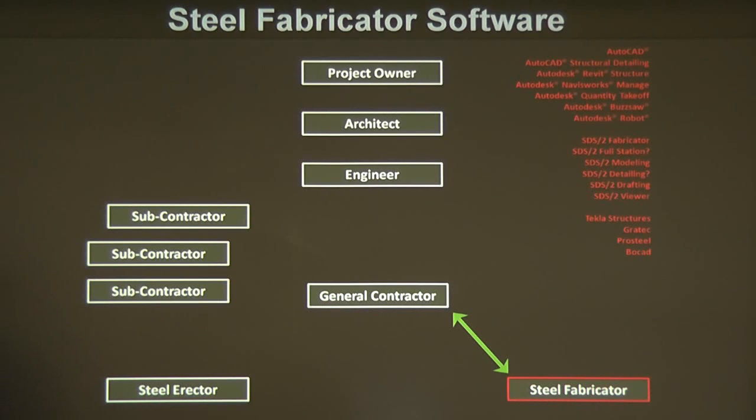The ideal situation is I don't want to get a set of 2D drawings and then start up SDS2 and re-input the model that you guys already built in Revit, right? I want to take the Revit import, bring it into SDS2, and create these drawings. It's a good question, and I will show you some of the drawings and what they do there.